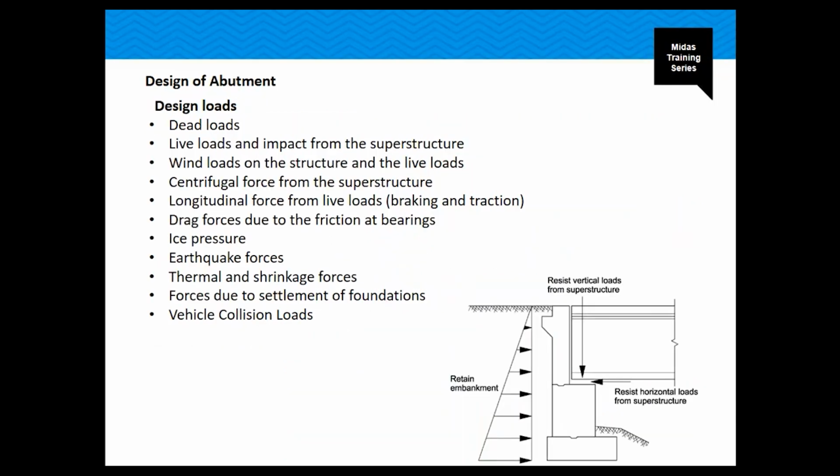For the abutments, we have to consider different types of loading, and also depending on the type of abutment that we're using, there are some factors, as I mentioned earlier, that need to be considered. We have to consider dead loads. We have to consider live load, impact, winds, centrifugal forces. Sometimes the expansion and contraction, in case we don't have any joints, earthquake loadings, and so on.